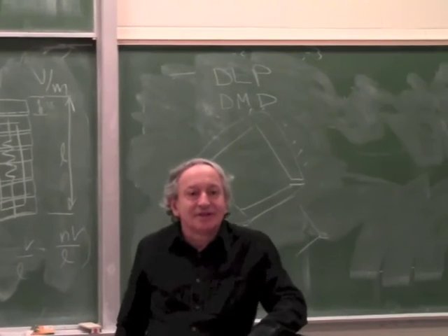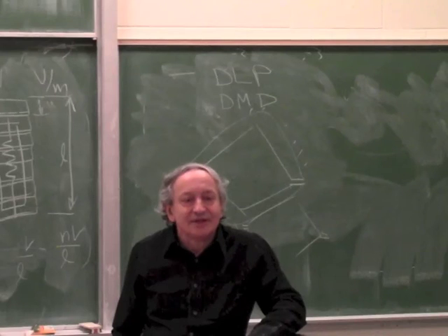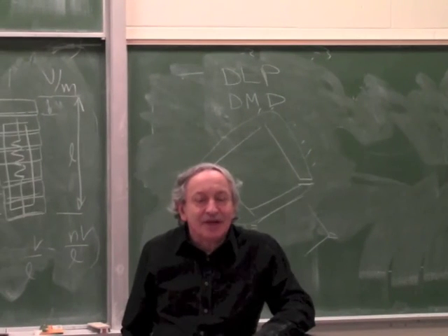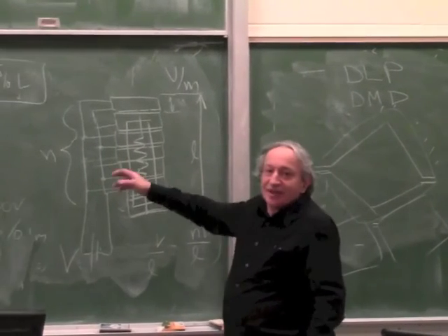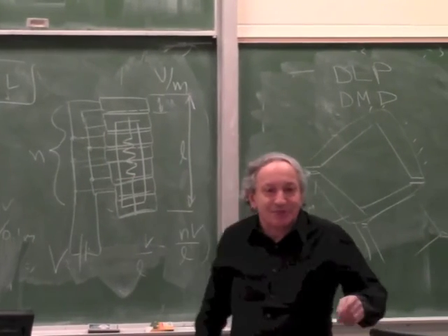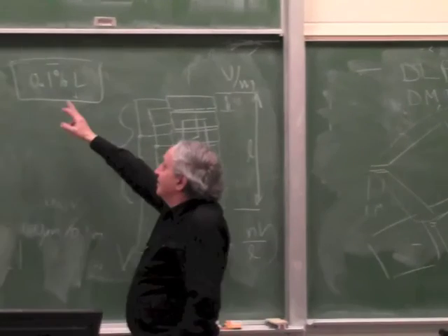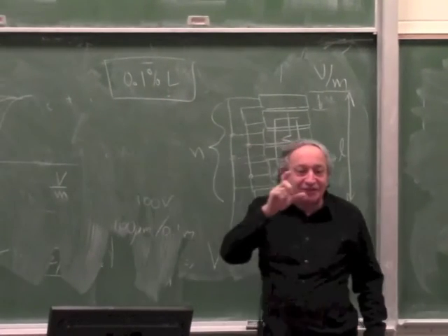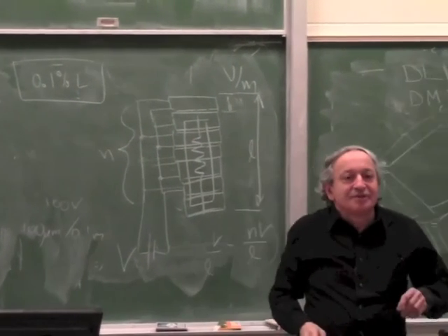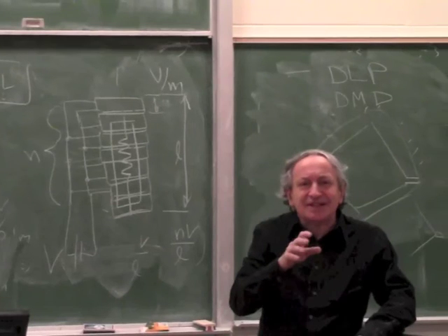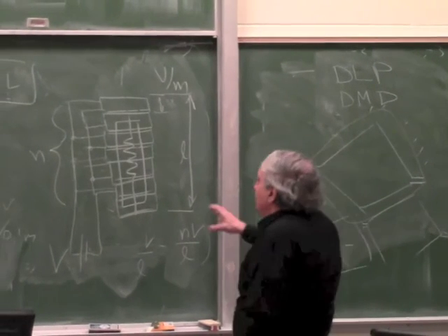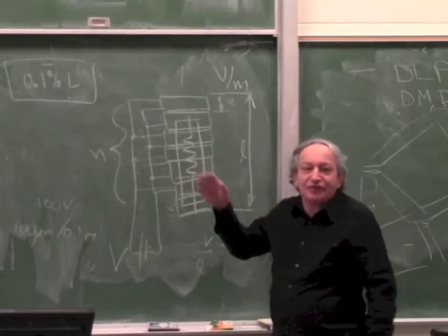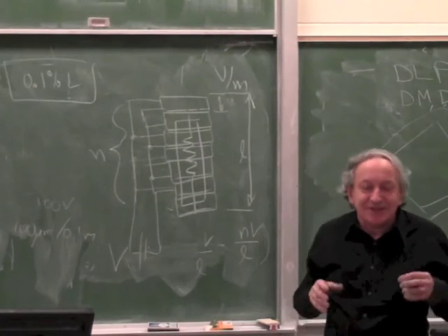Yes? Using that stack actuator with the strain gauge, what's the maximum accuracy? Like, what's your limiter? Accuracy is pretty good because now it's a servo. The strain gauge measures, so the accuracy should be as good as the strain gauge can measure, but you're still limited to that. That's really the problem. You still get very small motions. And there are other subtleties. Superficially, you would say that should be a very good actuator because I can move it very fast. There are no moving parts, but that's not so.